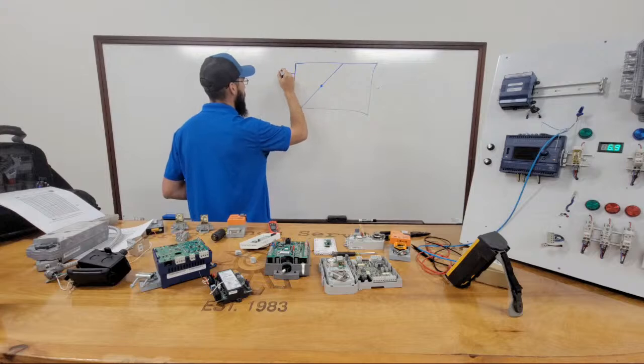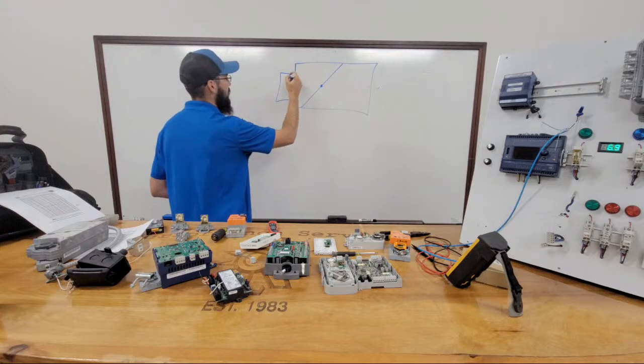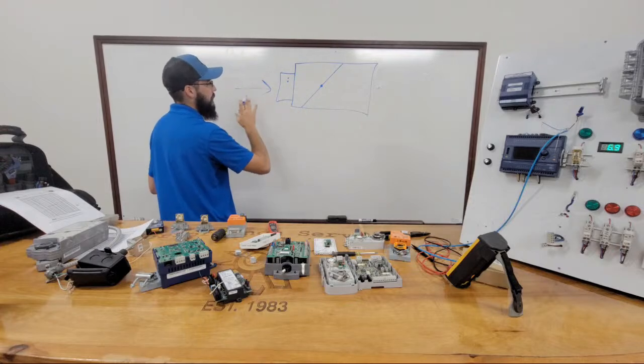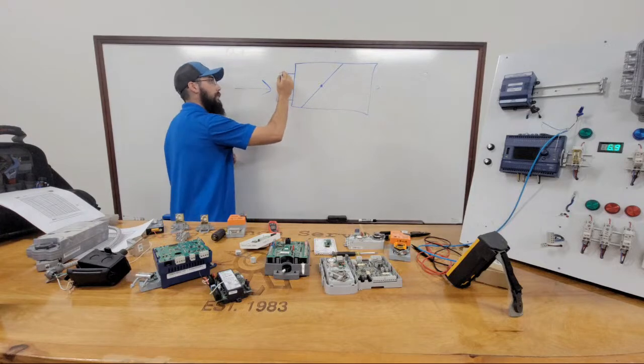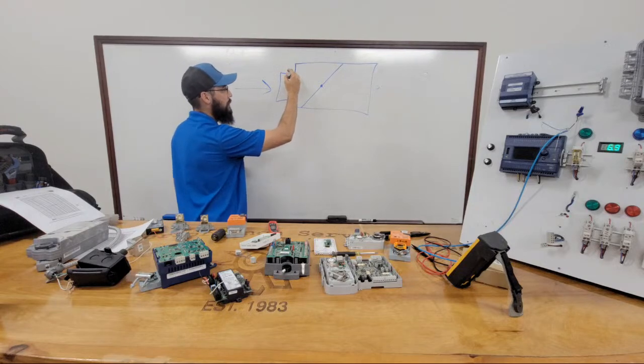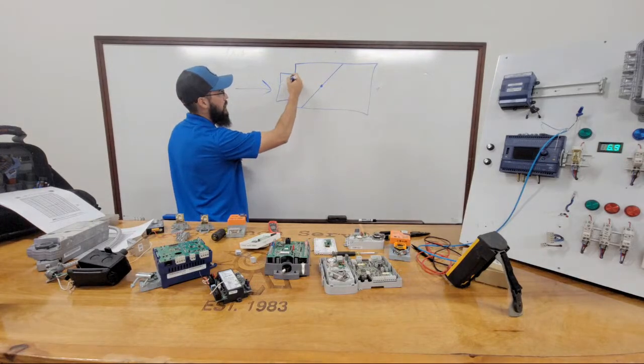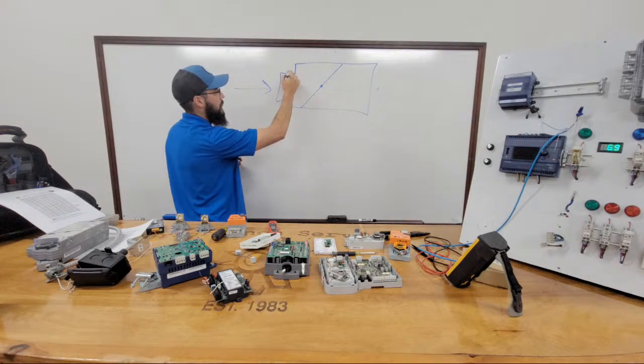You've got your round collar sticking out, and you'll have two little ports. All right, air is moving this way. Now, memory serves, your top port is going to be your high port, and your bottom port will be your low.